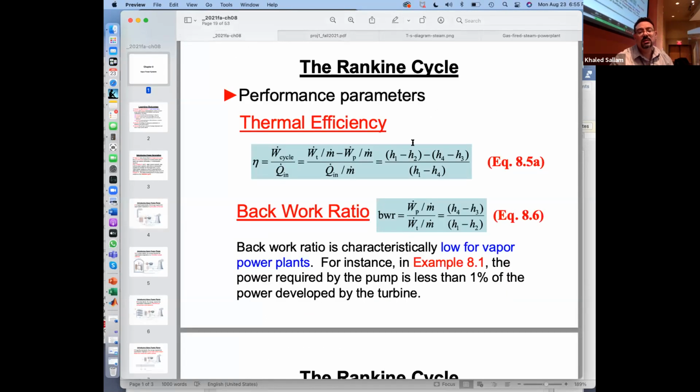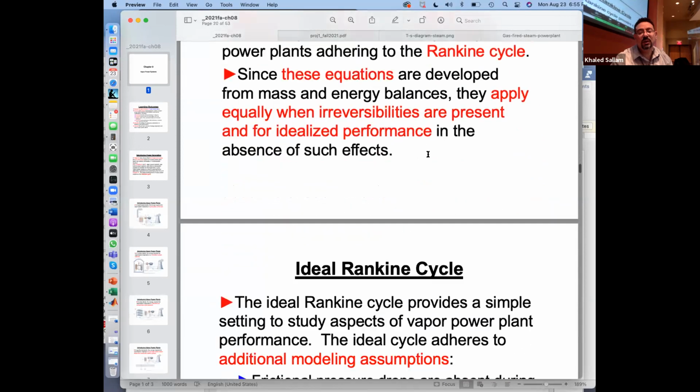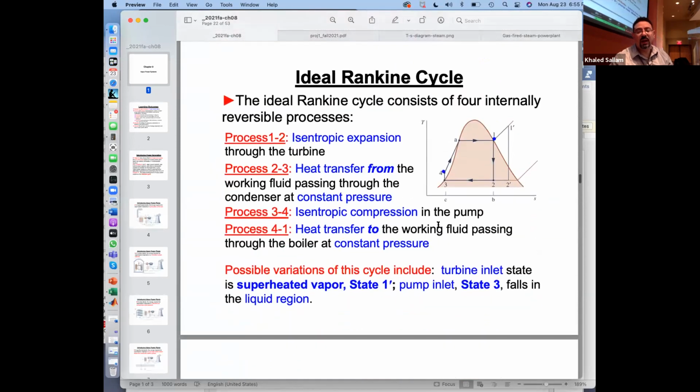All right. So this is pretty close, right? The ideal Rankine cycle, I mean, it's like this, but we cannot do this. We cannot go and hit the turbine with a bunch of droplets. So you have to superheat a little bit. You have to dry the vapor, make it superheated. And so by the time you come here, you are a little bit drier, so that your low pressure turbine does not get hit with quality like 0.8; you get 0.9, 0.95, right? So it's a little bit dry.